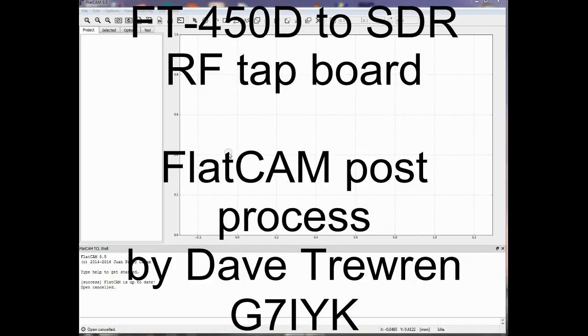Okay, hi everyone. I thought I'd do another little video of the next stage in the procedure, if you like. The first stage from the first video was using EasyEDA, a web-based PCB design package, and I didn't go through the whole process. I quickly went through going from the schematic to the PCB, then how to place a few components, and then ultimately export the Gerber files. Gerber files being the industry standard file description for PCBs.